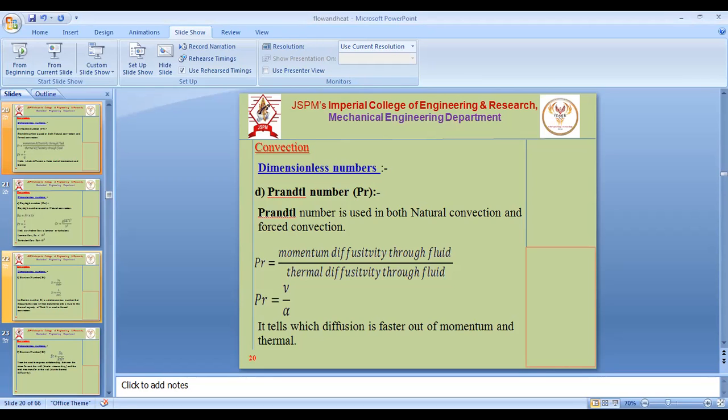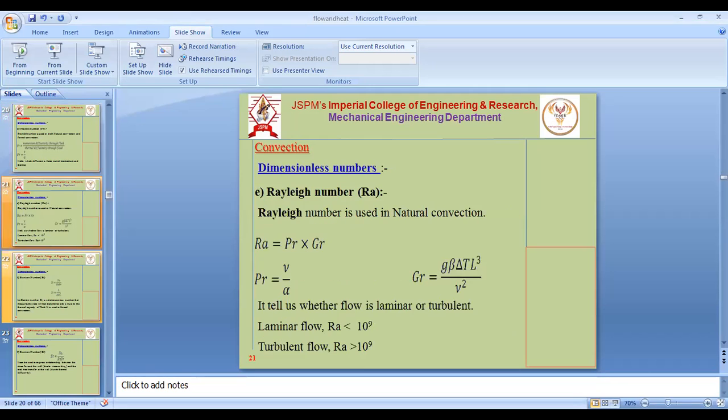We know that the Prandtl number for air is about 0.7. What's the meaning of that? Which is dominating, thermal diffusion or momentum diffusion? For air, the Prandtl number is 0.7, so thermal diffusion is bigger than momentum diffusion. Which diffuses faster, velocity or temperature? Temperature diffuses faster for air, but it is nearly 1.